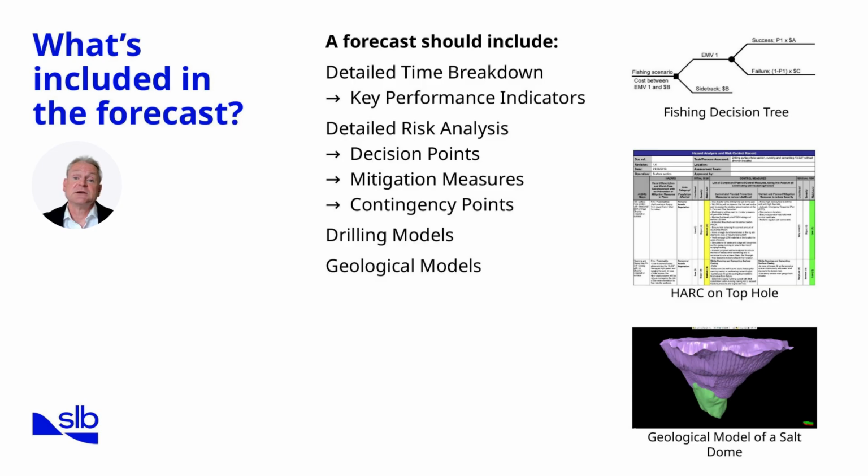Next, the forecast includes a thorough risk analysis. This covers decision points where the operation may need to adjust course, mitigation measures that outline how to respond to identified risks, and contingency points that ensure backup options are always available. Drilling models form the backbone of the forecast. Torque and drag, hydraulics, mechanical earth models, and time and cost simulations all provide predictive insights.